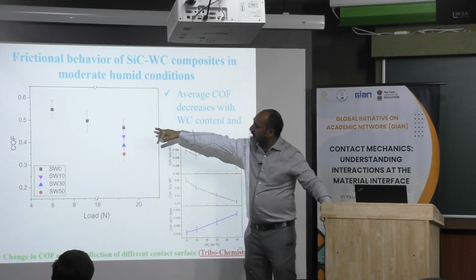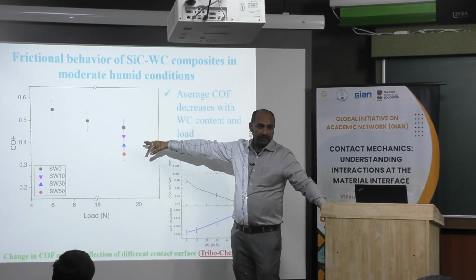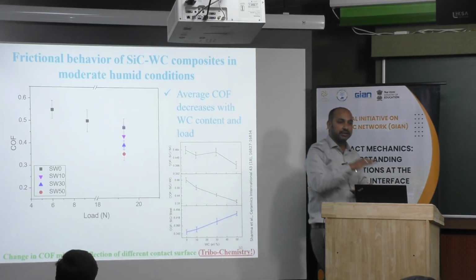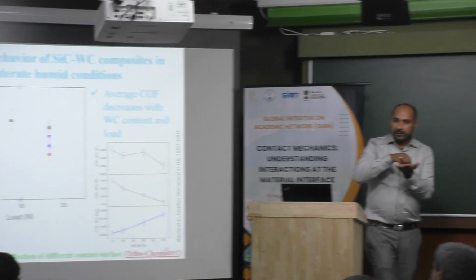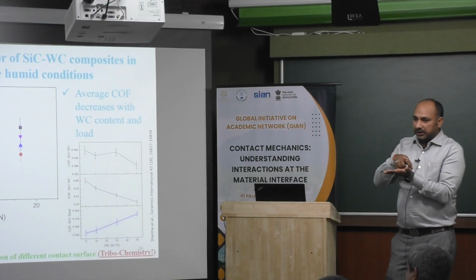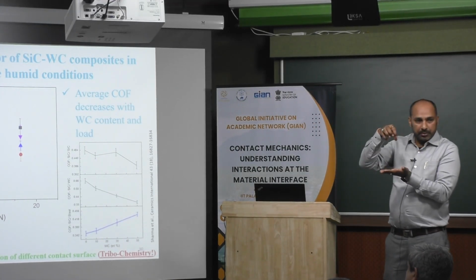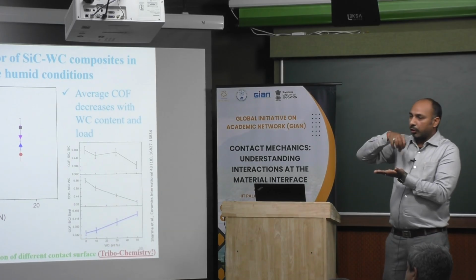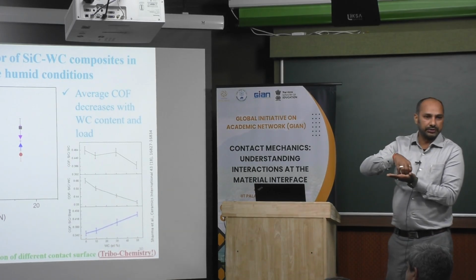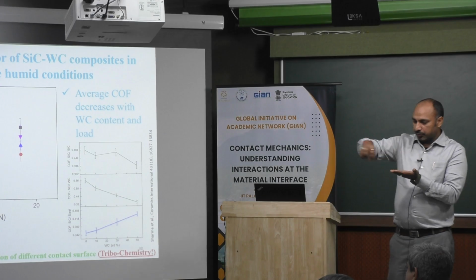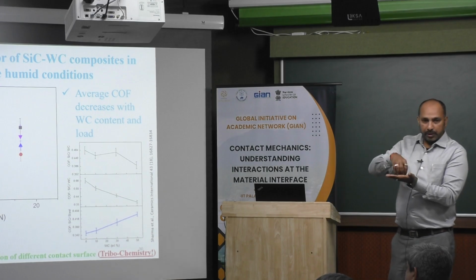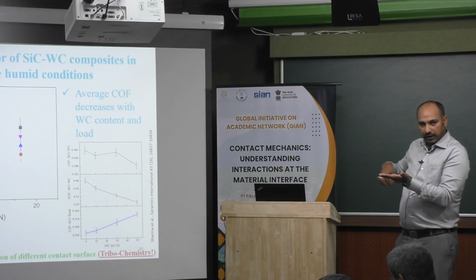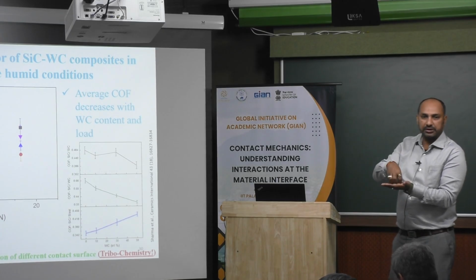But in the moderate humid condition, when we change the configuration, whatever debris is forming inside stays intact for a longer duration, and the debris to counter body contact time is increasing. Once we move over the complete surface, debris comes in contact, we come out, and debris comes in contact again when we reach here.